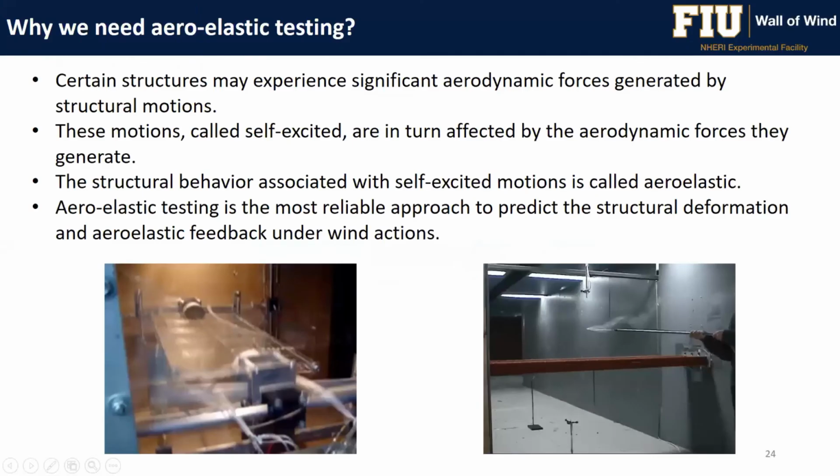Okay. So if I want to take one step back, one assumption for the aerodynamic testing that Johannes discussed is that we assume and we make sure that the models are rigid, very rigid. So the pressure measurements are not affected by the vibration of the structure. On the other hand, we understand that structures are flexible. Some of the structures are very flexible and they experience significant aerodynamic forces generated just by the structural motion.